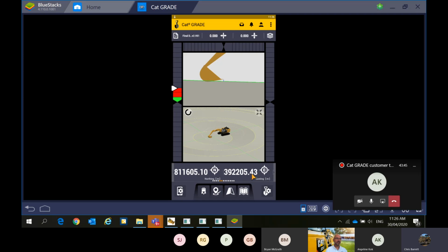Well, first things first, and this is something we really strongly recommend: before you go digging too far, to keep that cranky foreman off your back, go check the machine on a known survey point. When the job's done, there's a control point that's going to have a northing, easting and elevation value. Using that text ribbon we just set up, we can look at the elevation and the easting. This verifies quite a few things. By putting the machine on that known survey point, it determines whether you've got an accurate machine, a good bucket measure up, and that the site calibration is okay. So first thing you do before you go to work, if the machine's near the go line or you've just come onto a new job, make sure you verify the machine on a known survey point.